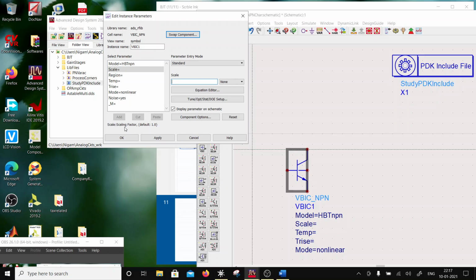Okay, so what I have is a 0.5 micron width, which is fixed here, and then I'm scaling the length. So let's consider something like 5. So now if I scale with 5, it will be 5 micron, right? And then I have a multiplicity, so let's say that multiplicity is 40.